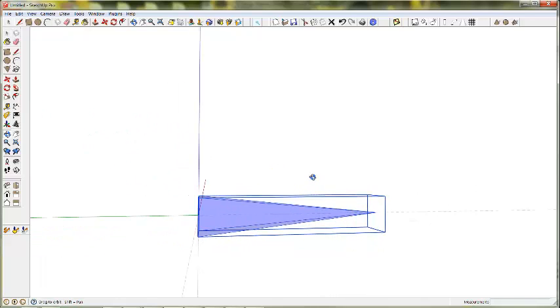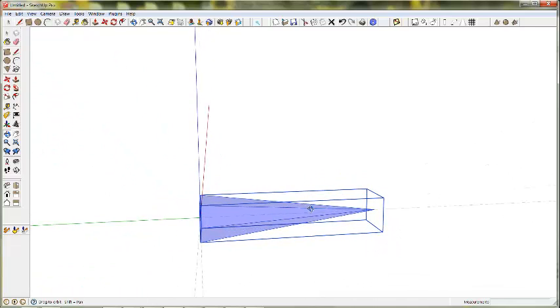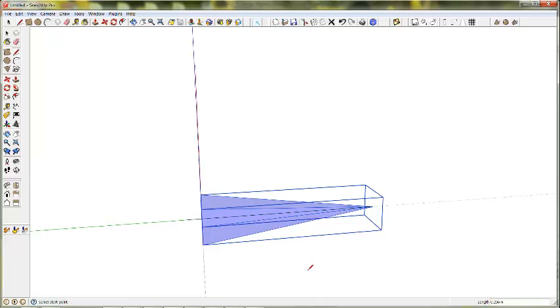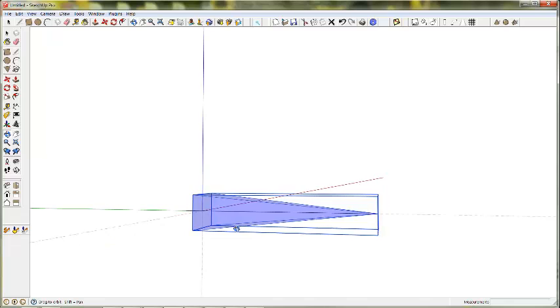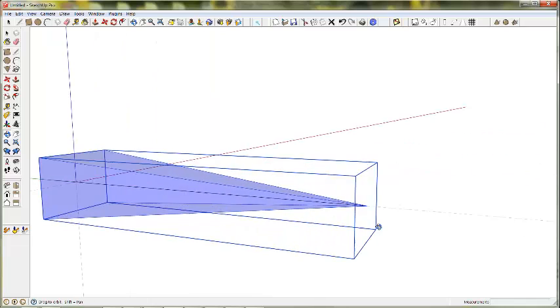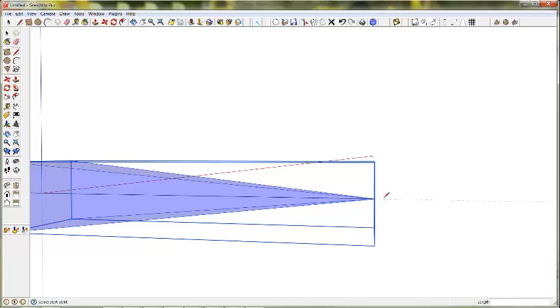Alright, one more enhancement I like to do is create a line right down the center. So draw a line beginning at the beginning of where the imager is, right along the green axis there, and maybe extending 1 meter past the front of the face. It just gives us a reference point and shows us where exactly we are within the field of view. It's a good reference when you're placing the image or trying to decide where you are, and just it's a helpful pointer. So we add that line in real quick, and basically just use the line select tool, draw it out there, enter the value in, and we're good to go.